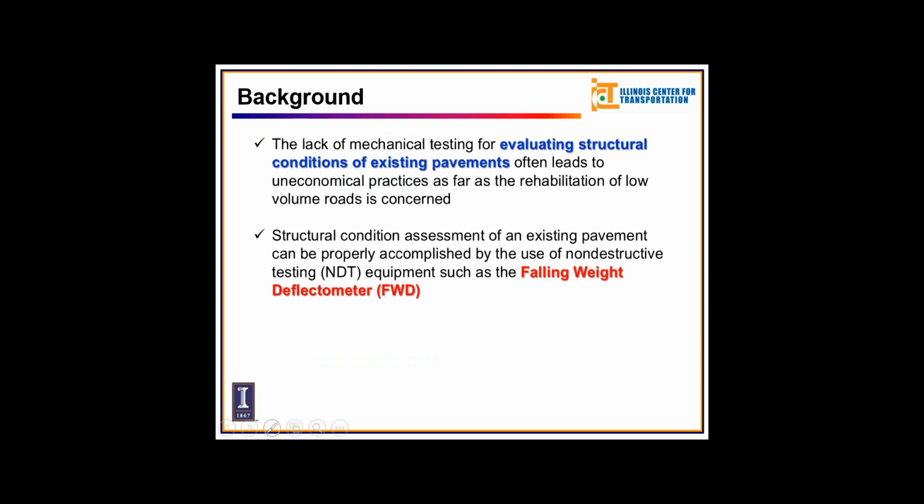And sometimes the pavement is actually in very bad shape, but the design requirement says that you only need a thinner overlay. So in no time the pavement will fail and you will need another overlay. This can often result in uneconomical practices. So it's very important to do a proper structural condition assessment of an existing pavement structure before any overlay design is done, and it can be properly accomplished by the use of non-destructive testing equipment such as the falling weight deflectometer.